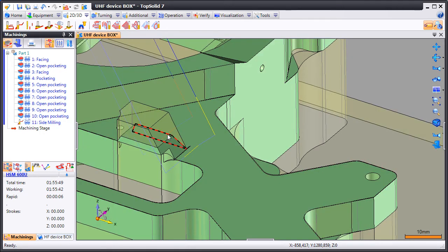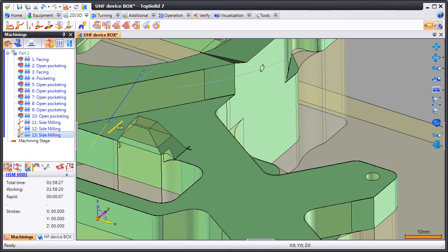And even when we're cutting with the side of the cutter, we can dynamically drag and drop copies to other faces around the model. Now watch what happens when we drag and drop a copy to this face back there. Watch the lead out position. You'll notice that it automatically avoids the wall in the back. How smart is this toolpath?